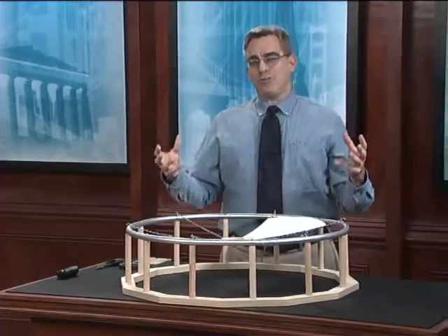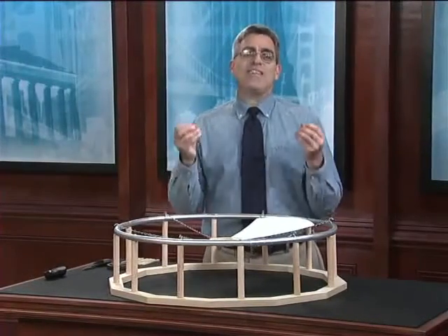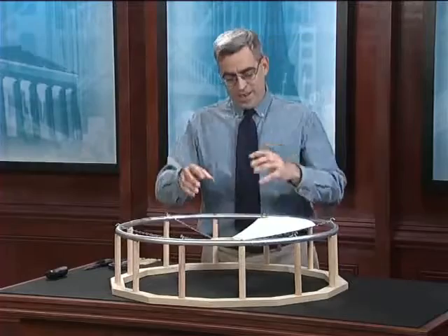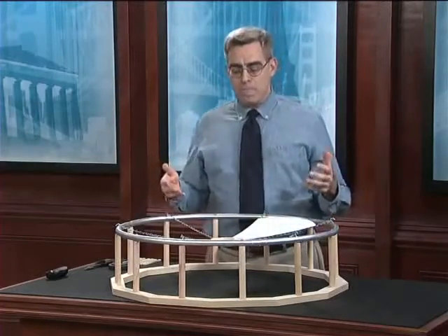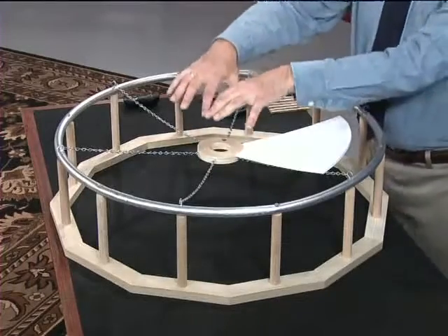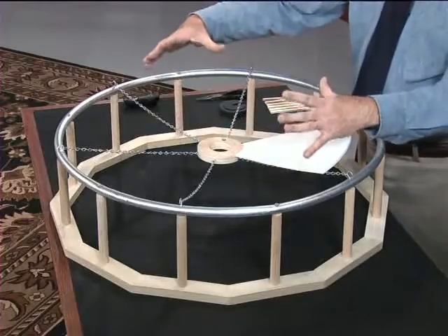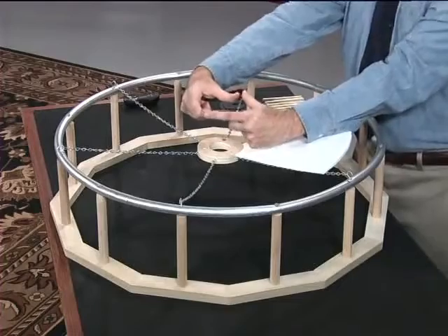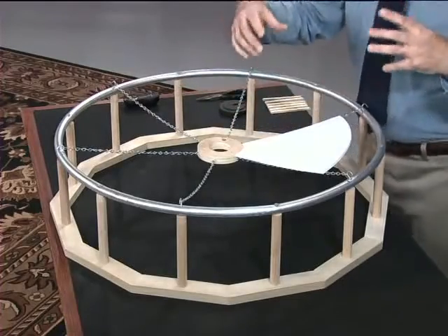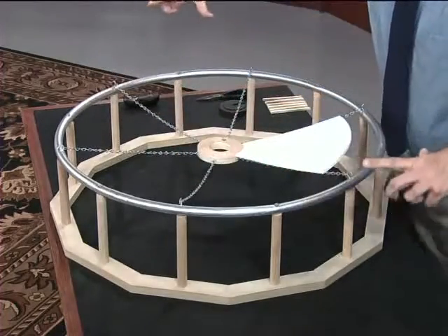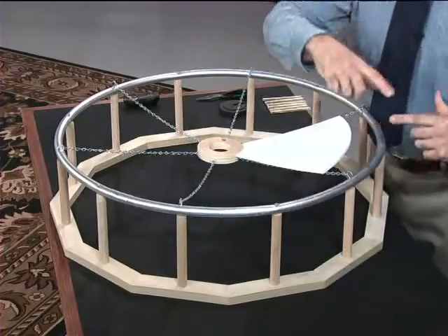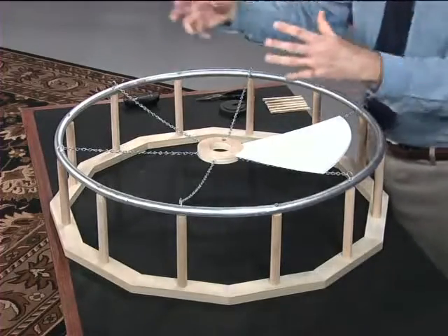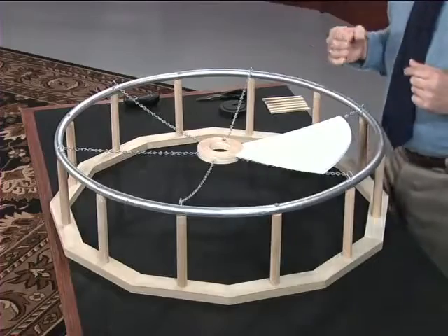This overall structural system is a thing of beauty because it demonstrates equilibrium in action. The cables, of course, are in tension. The cables are all pulling outward on this central ring, so they're placing the inner ring entirely in tension as they try to expand it outward. At the same time, the tension in those cables is pulling inward on the outer ring, and so the outer ring is actually called a compression ring. And as a result, the entire system is in balance.